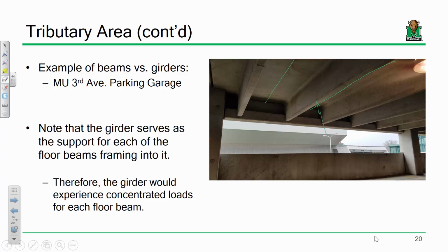Okay? Whereas this one, that's a lot different. And the reason it's a lot different is because as soon as I fix that in, remember if we had a beam that looked like this and it had a fixed support like that, this support behaves a lot differently because not only does it have a reaction that goes like that, but it also has a moment reaction, right? So that does change what the moment diagram looks like. So these conditions we call fixed supports.